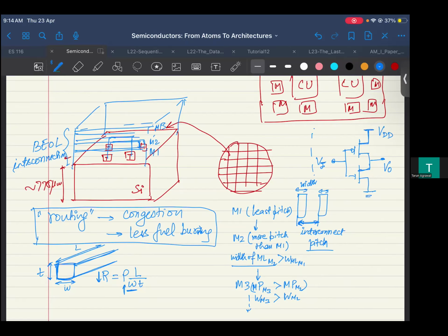And I think we have talked about it in some video on DRAM, or when we were talking about transistors, the different avatars of transistor. And we talked about that this Vi is giving you this NOT operation. So basically this is Vi bar. This is the basic NOT gate one can build, and these two are supply lines. This is the ground supply line, and this is your VDD, or whatever your high voltage supply line.